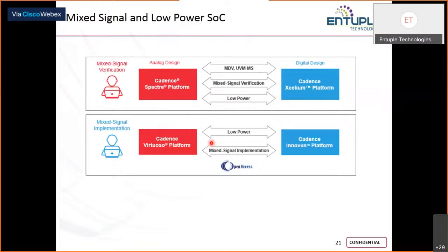Particularly for today's topic, since the sessions are about mixed signal and low power mixed signal design, you have two types of designing aspects. One will be analog on top, and the other one will be digital on top. So what you can do is start your design on Virtuoso, get the files, or create your Verilog or VHDL files, and then import it into Virtuoso. Then build your layout: layout of analog systems on Virtuoso and digital systems on Innovus. Then combine both the things and complete the entire design.